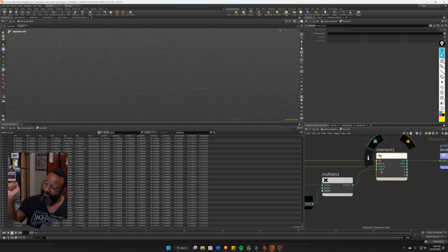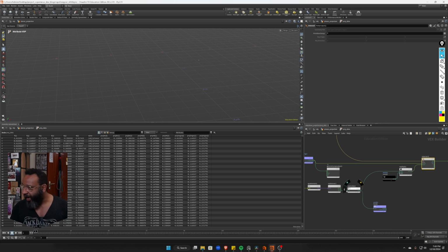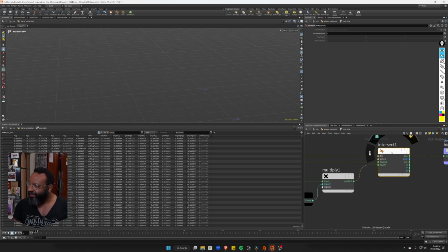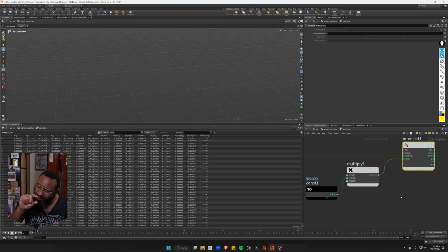So you have your point in space and where do you want to point it, where do you want to shoot it? That is my Z direction, so that goes in here. There is one thing: I tried this and I was pulling my hair out and couldn't get it to work. Then there's one little note at the bottom of the documentation that says it will only pick up surface hits if the ray is longer than the distance to the surface.